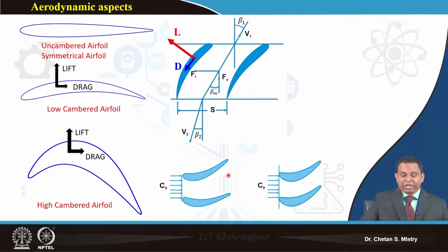Now if this is your case, just look at this second arrangement. Okay. Here, if you look carefully, I have my entry area, and this is my exit area, and my entry area is larger and my exit area is smaller. Okay, that means it is making a converging passage or nozzle kind of configuration. So from now onwards, as and when you look at the blades, you must realize whether it is a compressor blade or a turbine blade. What are the two ways? Just look at what is happening between the passage and look at the camber of that airfoil, or the camber of that particular blade.